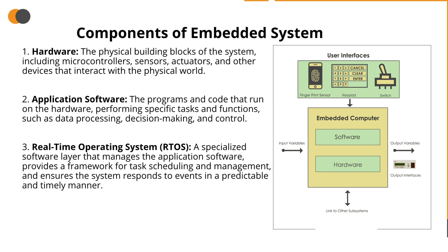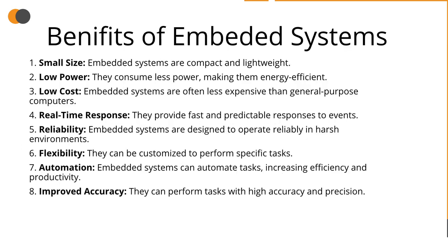As we said in the above components, hardware will be microcontrollers, memory such as RAM, ROM, EEPROM, input-output peripherals such as GPIOs, UARTs, and sensors and actuators. While the software will be firmware, which is coded in Embedded C, an operating system which is optional, as we said, some may not use one, and device drivers and application software.